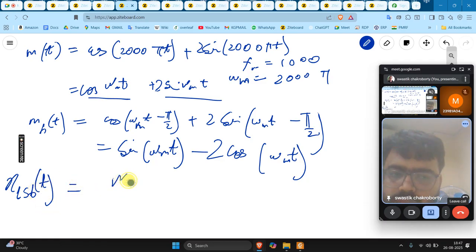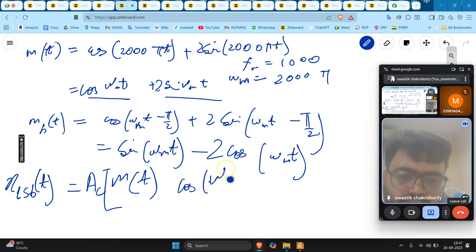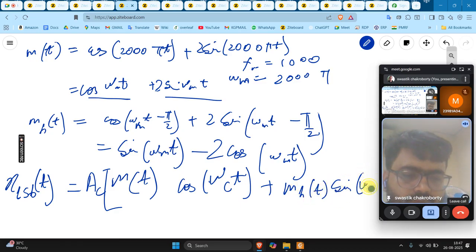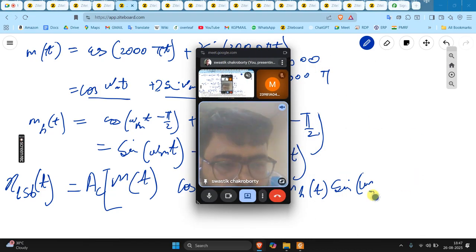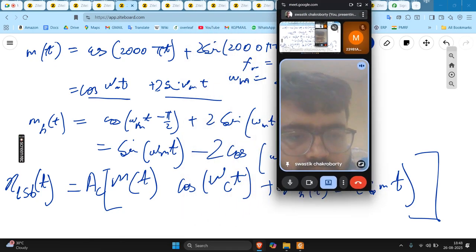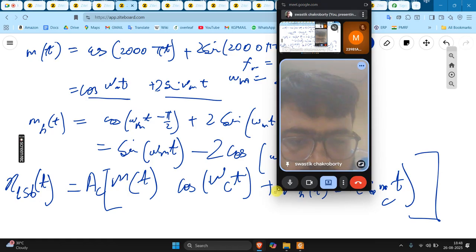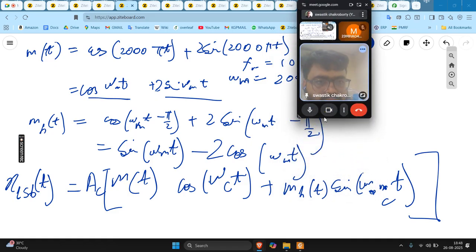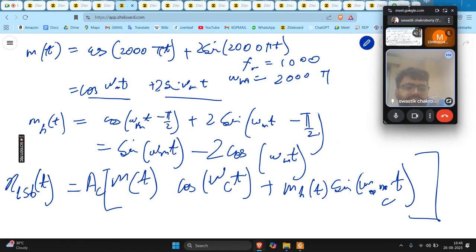The LSB will be Ac times m(t) cos omega c t plus m_h(t) sin omega c t.